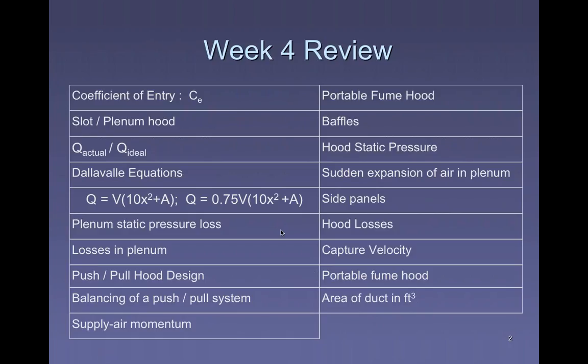We talked about capture velocity, how fast the air has to be moving at the distance where you're working with the contaminant in order to capture that contaminant. And it's not mentioned here, but we also brought up the idea of transport velocity. Once that contaminant is captured and pulled into the hood and into the ductwork, you've got to make sure the air is moving through the ductwork fast enough to keep it from settling out in the ductwork as well. That's transport velocity. We're going to be looking at that as we build our hoods.